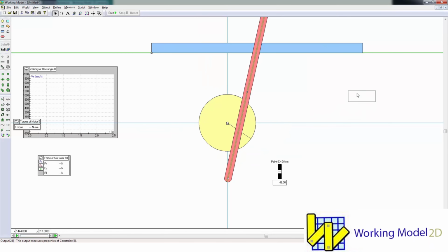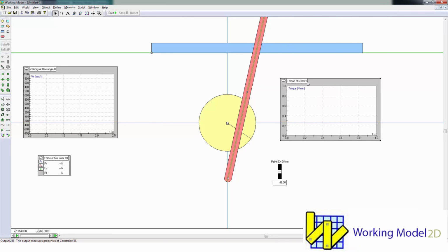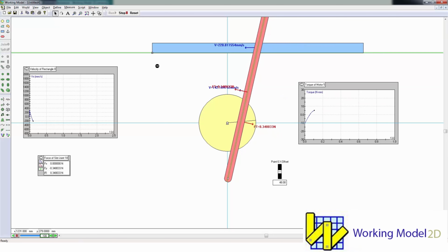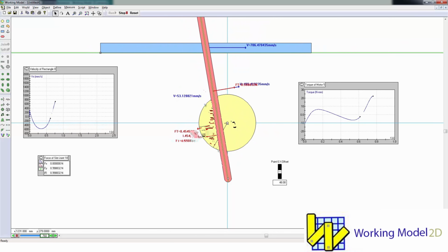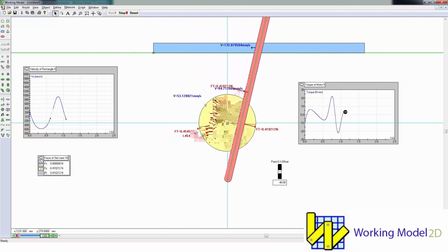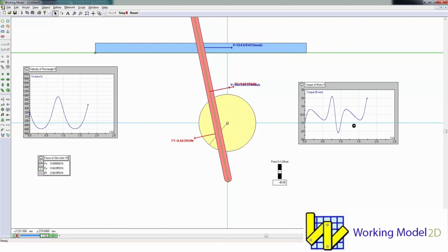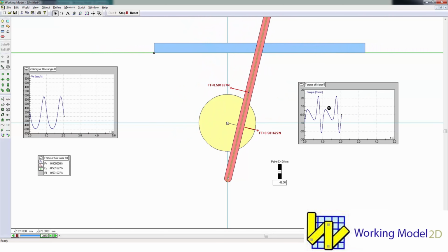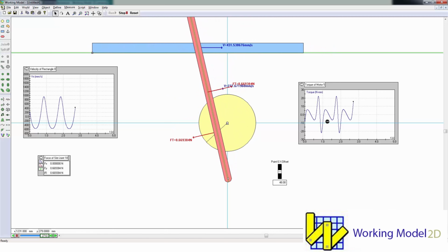And then we can make changes to the model and begin adding that complexity through friction, different resistance and things like that, any load this thing might be moving, and we can study the effect on that. So let's go ahead and just enlarge this meter for the torque a little bit. And now if we run this simulation, this is rotating at a nice constant speed like we specified, 360 degrees per second, but as a result, this is the torque profile required to achieve that constant velocity. So if we were to export this curve to Excel, for example,